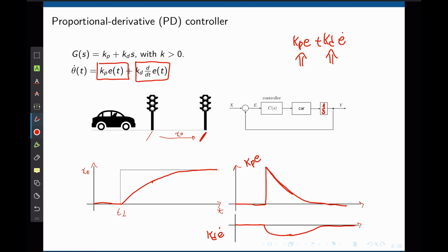With some abuse of terminology, we can say that the derivative gain in this example is added to look at the future behavior of the system by looking at how fast the error is changing and in which direction the error is changing. If the error is decreasing, the system is responding to the commands. The derivative of a decreasing value is less than 0, so we can now decrease the overall control effort. On the other hand, if the error is increasing, then you have to take more actions to bring the error back to 0. We now increase the control action to do that.